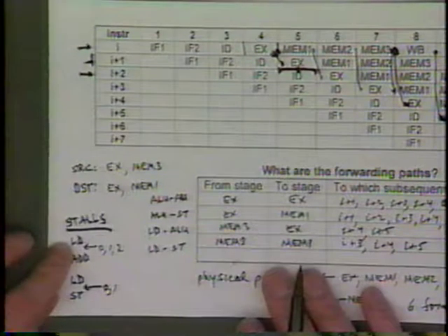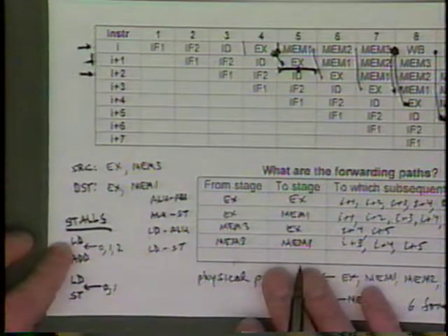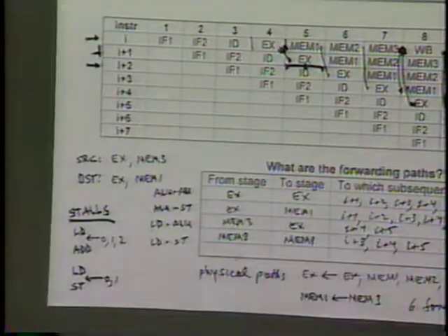In that case, couldn't it be even reduced to 0? I mean, if the next instruction is completely unrelated to the load? If the next instruction after the load is unrelated, yes. Certainly if you put enough instructions, 2 or 3, in between the load and the thing that needs it, then the delay is 0.